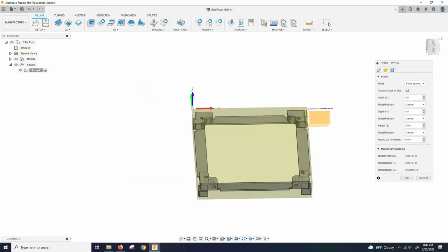So we've got that, and then it gives us 4 inch by 4 inch. You could bump this up a little bit. Your X, you can definitely keep at 4" because you can basically use that as your stock size if you buy 4" stock. But then the length, you're going to be cutting that off on like a bandsaw or something. You could give yourself a little extra leeway if you're worried about hitting these dimensions. You can make your width 4.25 or give yourself like 4 1/8 or something like that. We'll keep it like this for now.